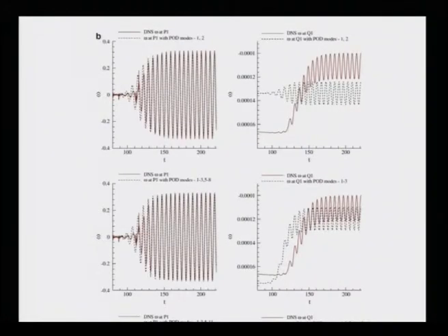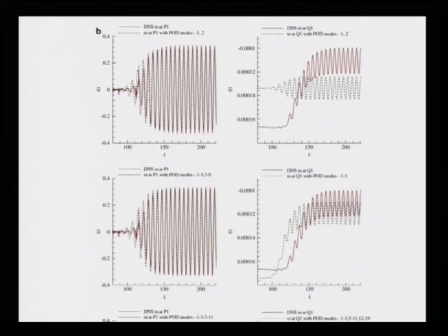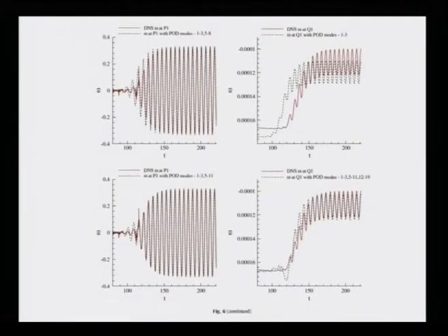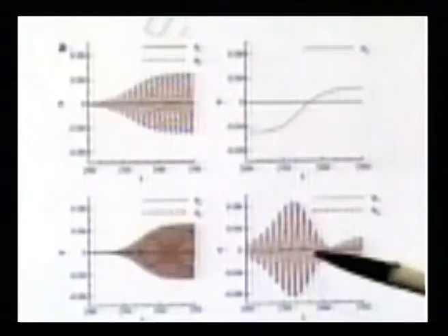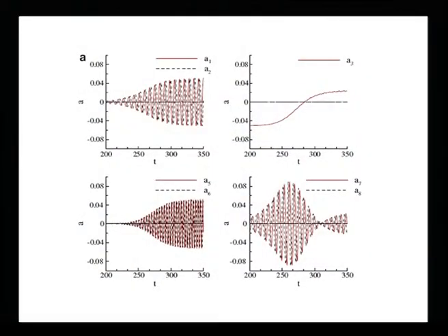These are those mode shapes for cylinders. Anyway, what we are essentially looking at is a mode shape for flow past a cylinder at Reynolds number of 60, and again you can see these two are the regular modes. This is the T1 mode and this is the T2 mode, and so on and so forth. So you can study these as universal building blocks. Okay. So I think I will close the discussion here on POD analysis. I suppose you have now seen quite a bit of variations.